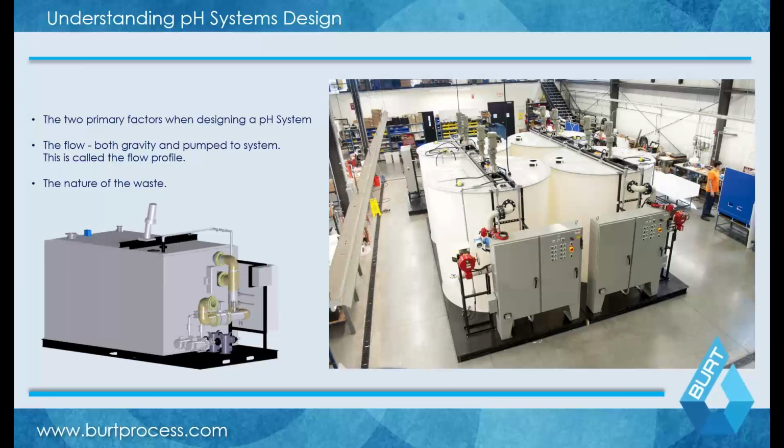The first is the flow profile of your waste, whether you're pumping your waste, whether you're going to have a gravity-based system, or some combination of that, because you need to understand the flow rate of this aqueous waste discharge. The second is the nature of your waste: the chemicals involved, what type of building it is, and any special waste constraints. For this conversation, we're not talking at all about sanitary-based waste. This is purely process waste, really an aqueous waste-based pH system.